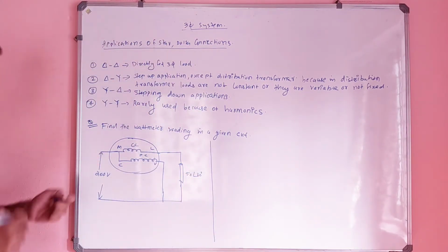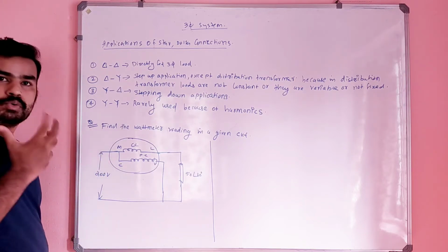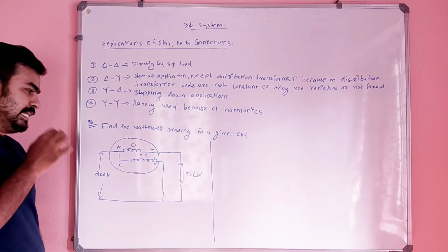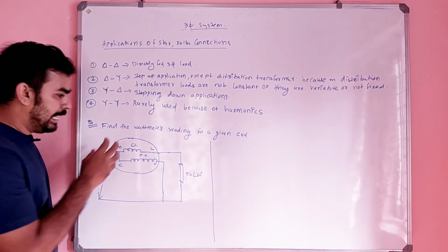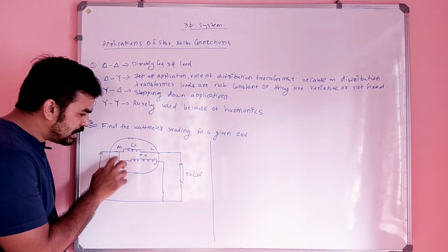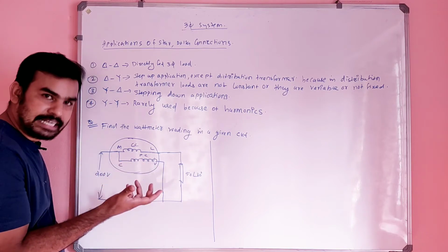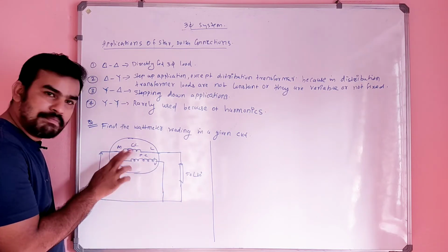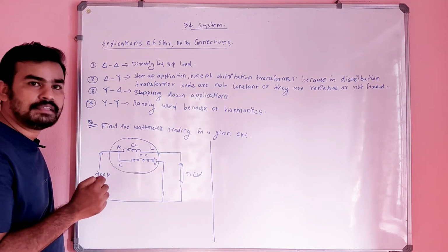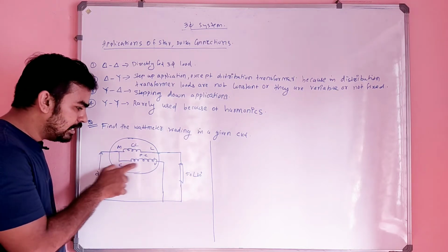See, what does a wattmeter normally do? It measures the current through it, and the voltage across its pressure coil, and it simply multiplies those two, and multiplies one more thing, that is the cosine of the angle between that current and that voltage.